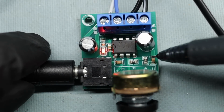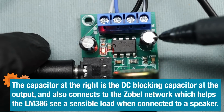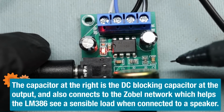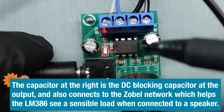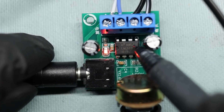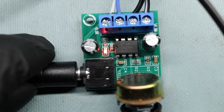And we have all of our components down here that set up the gain. This guy is part of the DC decoupling capacitor. So we got a large value cap there just for safety. And yeah, you can see all the other resistors and capacitors that are part of the gain. Nothing connected to the top side here, so we're not manipulating that feedback loop like we looked at earlier. But let's give it a listen.